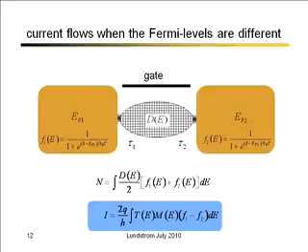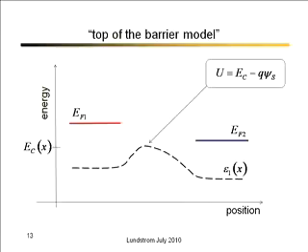So they contribute the density of states divided by 2 times the Fermi function. The ones that come in from the drain can only occupy negative velocity states. So they contribute density of states divided by 2 times the Fermi function of the drain. We'll need that a little bit later too. But those are the 2 equations that we need to understand the IV characteristics of this small MOSFET. Okay, so we want to map this MOSFET onto this simple picture of a nano device.